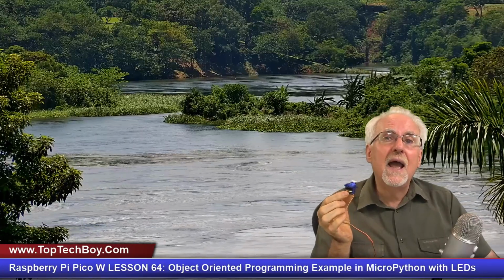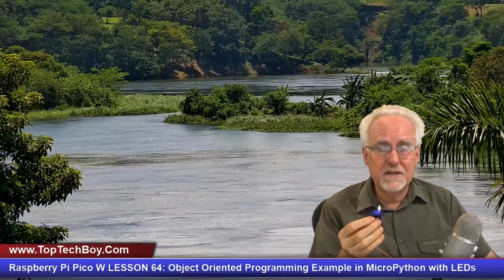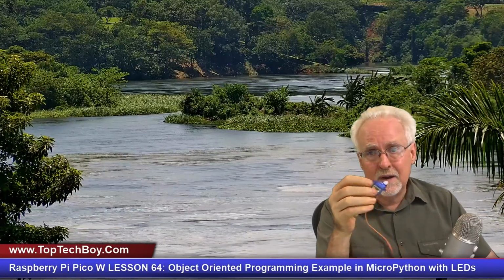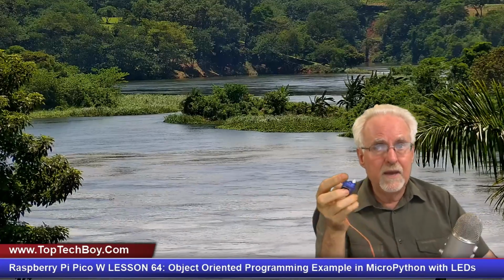And then I want to interact with this just by saying something like blue servo.pos for position, and then I want to give it a number from 0 to 180. So when I want to work with this servo, all I've got to do is just say blue servo.pos and then pass it the angle.